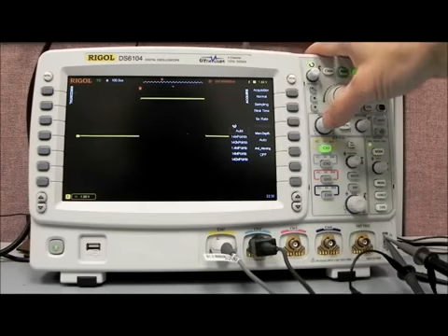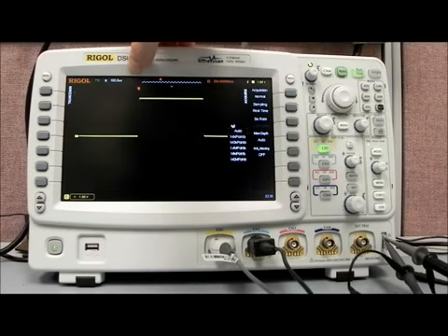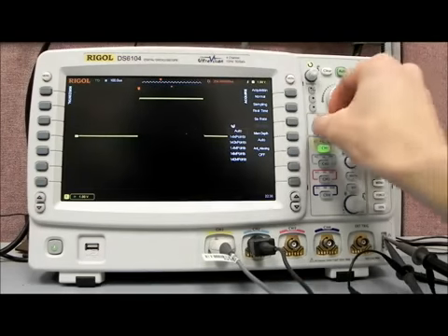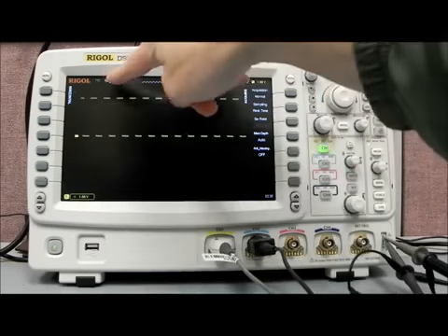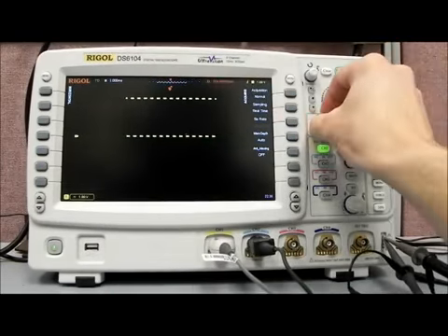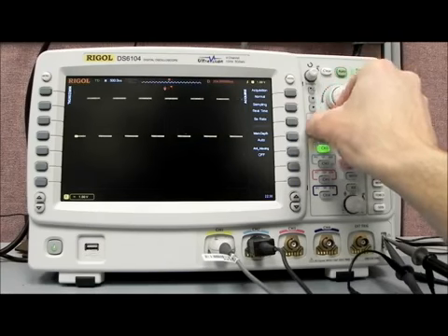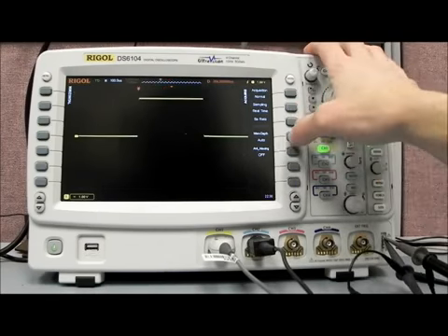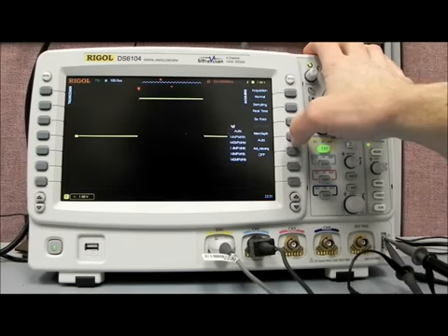Right now we're on the 100 microseconds per division time scale, and we're collecting at 5 gigasamples per second, at 7 million samples, or 7 million points. If we go down to 1 millisecond per division, we've gone up to 70 million points. And you can see now we're at 140 million on the 5 milliseconds, etc. So in auto, it's going to automatically select the number of data points that are collected. But we can also force the scope into a manual mode.